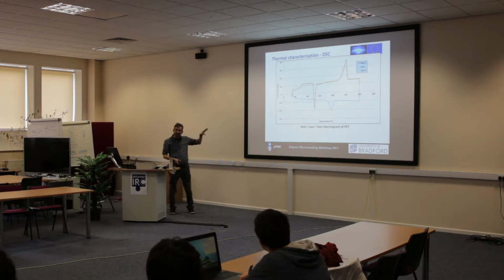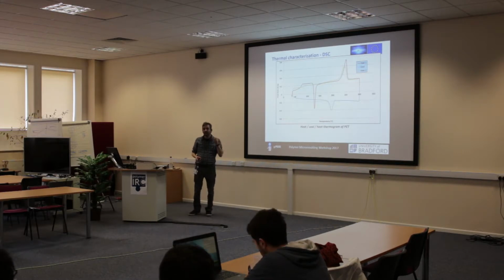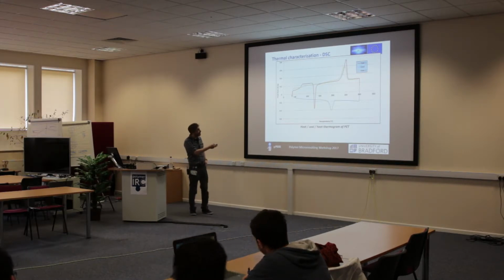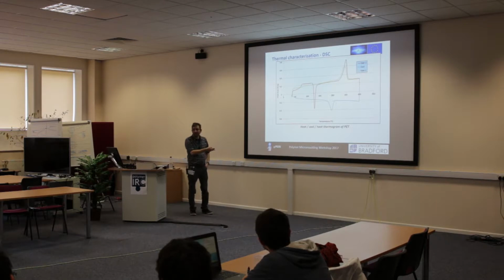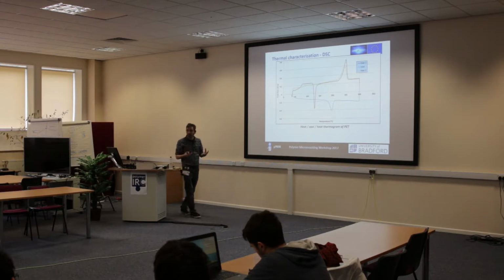The great thing with PET, and a similar material, PLA for instance, is that it doesn't matter. You can regrow it by holding it at this temperature. It's a thing known as solid state polymerization, SSP, and it means that your bottle is as good as new just by holding it at that temperature before you start processing it, okay? So you just heat it in an oven, it all comes back to form, okay?